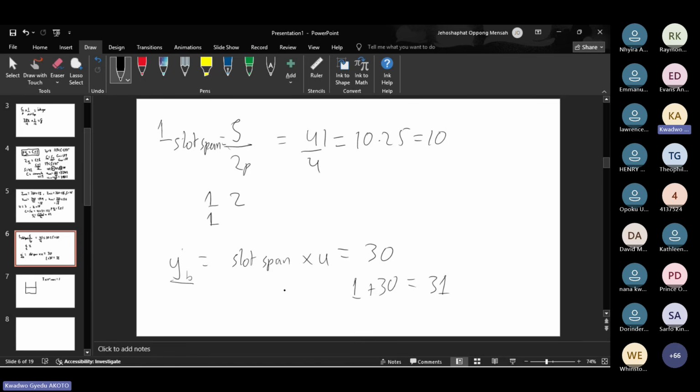And then we find our coil pitch, which is just trying to say that if I am coil 1, then my top conductor, I call it top conductor 1. Then my bottom conductor is going to be a coil pitch away from my top conductor, because the coil pitch is the distance between top and bottom conductors of the same coil, right?